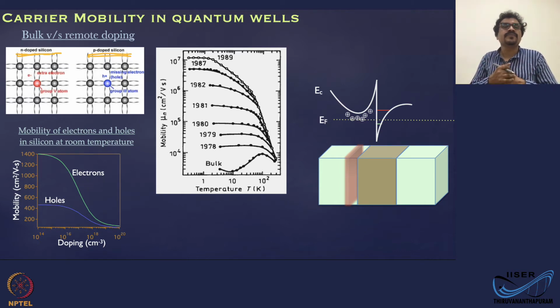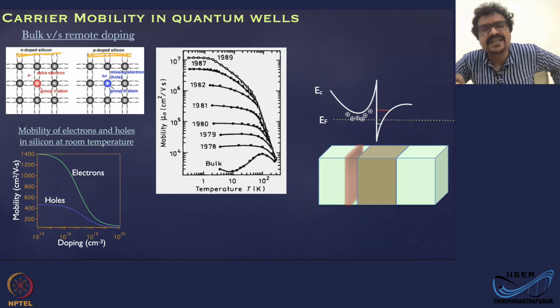On the other hand, if you put in far fewer impurities, then of course you can get a higher mobility. But again, mobility is also controlled by phonon scattering. So you have to go to low temperature, but at low temperature you have far lower carrier concentration, because these carriers need to come from the valence band, or the conduction band for N-type. Then you have absolutely no conductivity, it will freeze. You will not have any carriers. So it's actually a very tricky situation.